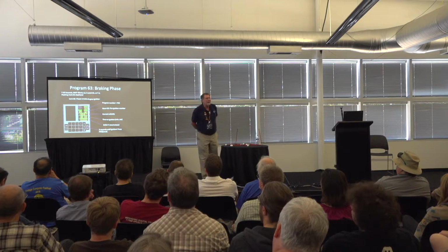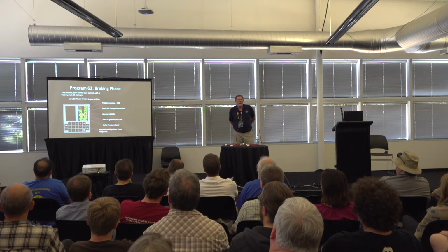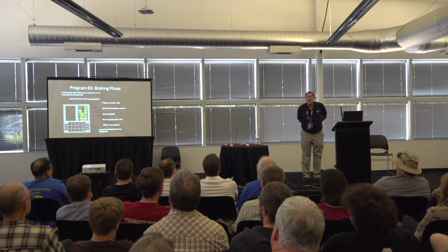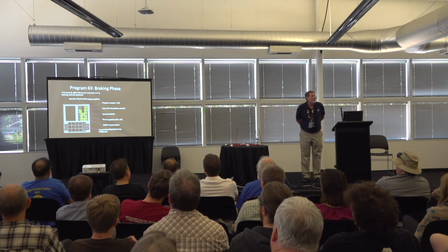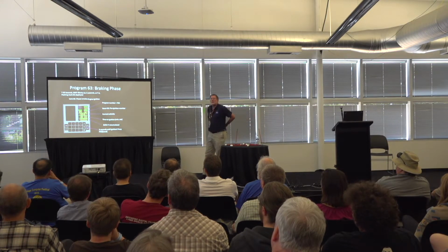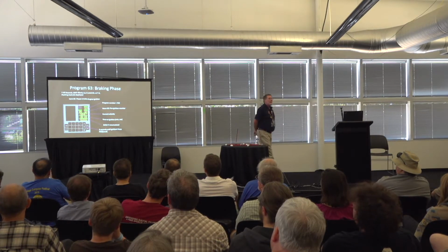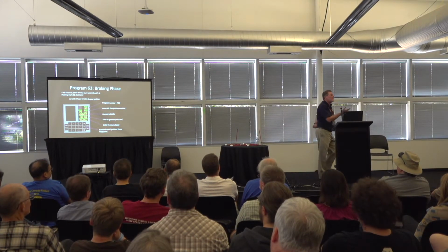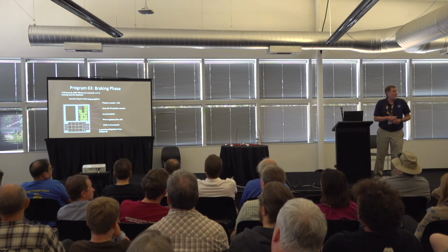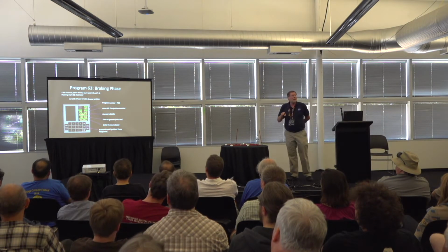Now, firing up the engine is, well, it's kind of a commitment, isn't it? So, like all good computers, they ask, are you sure? Are you really, really sure you want to do that? And the way it does it, it flashes a special verb, asking for permission. It's verb 99. Verbs actually work two ways. It's instructions for the computer. There's also a few verbs that it would like you to do. And verb 99 says, okay to go. And you just hit the button marked proceed.